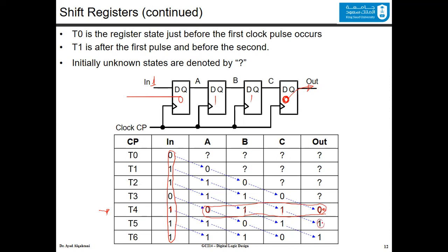In the next cycle, this will be taken out and the new one will be shifted. You can see the diagonal behavior of the inputs. The first one, 0, will be shifted each cycle to the next position. The next input shifts this way, and so on to the last bit.